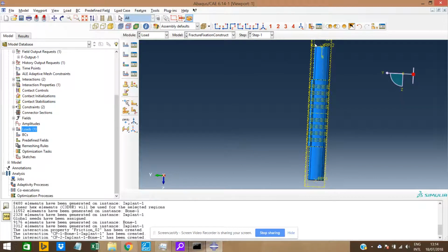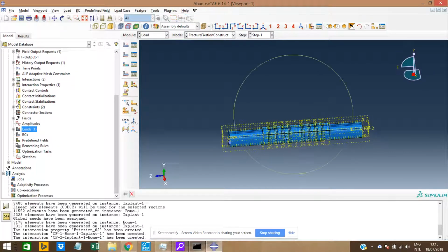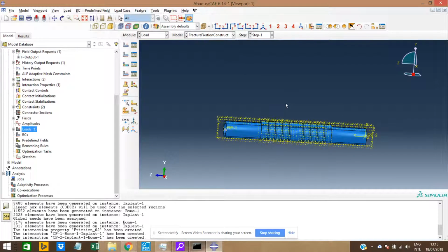And in which case, it would generate a moment. So if you say a force here of 600 newtons, then you multiply that by the radius, which is more, but let's say it was 10 millimeters, that's 0.01 meters, and if you multiply that by the 600, you end up with about 6 Newton meters. But then I'm making these times 1,000.